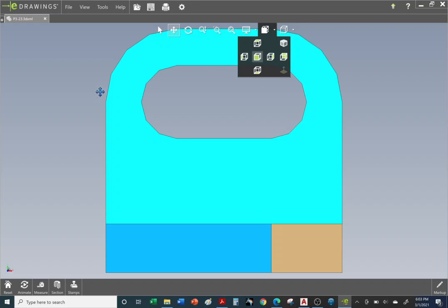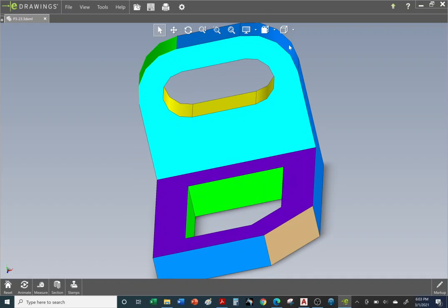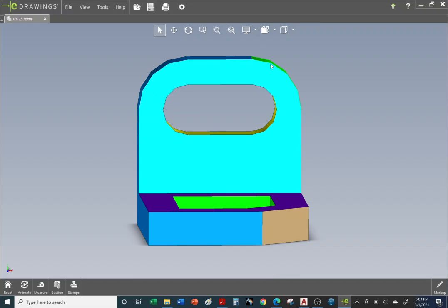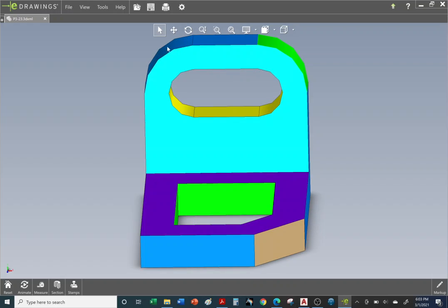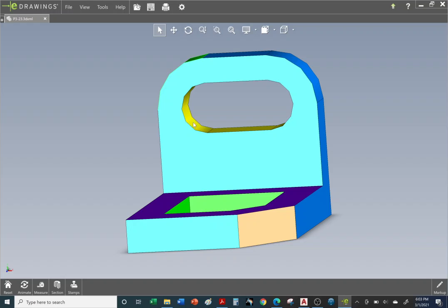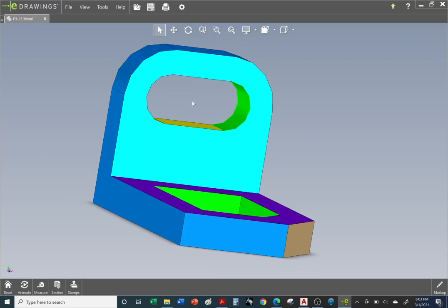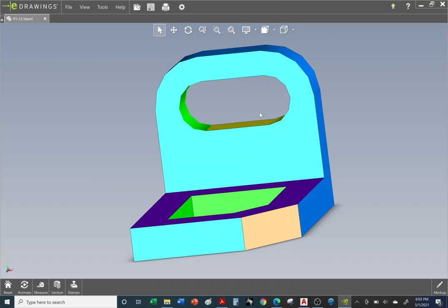Now the ones out here on the outside are 90-degree arcs. So we have this cylindrical shape and also this one. Since it's not a full circle or semicircle, we don't need green center lines for these. These are only 90-degree arcs. But we will need them for the yellow ones here. These are semicircles, right? Half circles or semi-cylinders, so here we will need center lines for the inside.